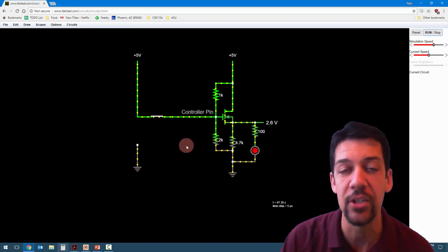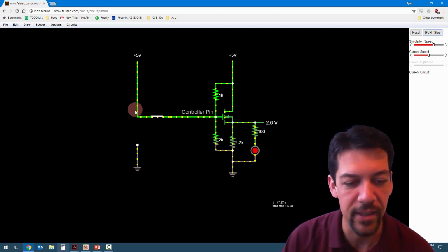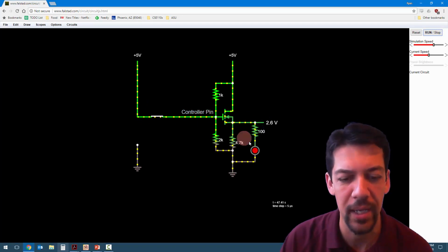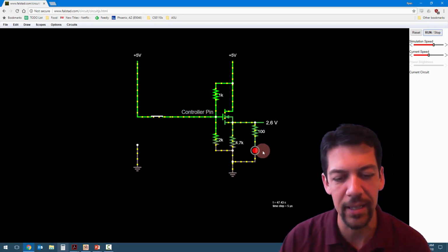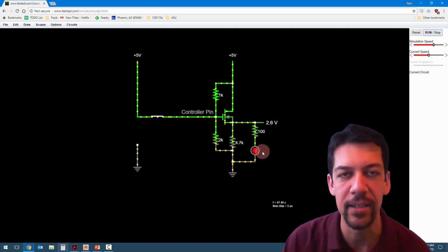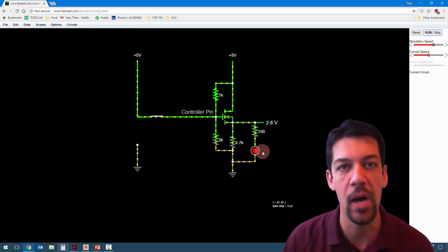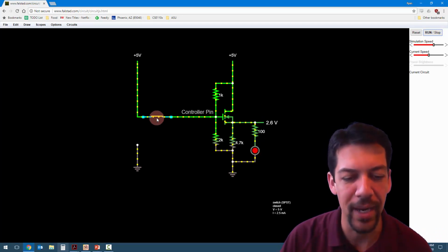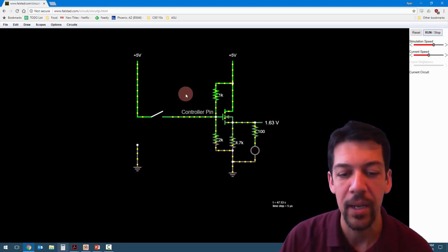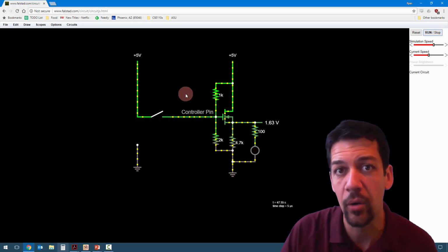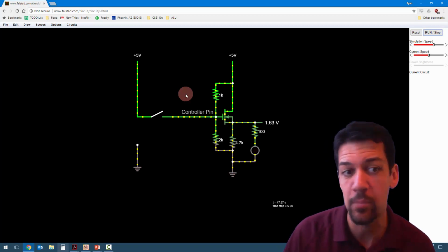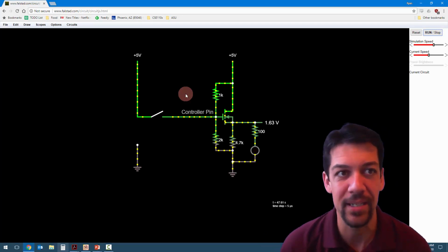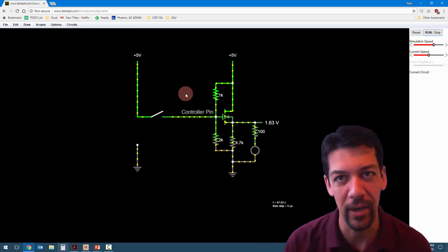When I close the switch, I do get the behavior that I want, in that the current flows through the switch into the microcontroller pin, and it turns it on. So my little LED indicator here in the circuit says, yes, I'm detecting a 1. This is true and on. Great. So the problem remains that when the switch is open, I get a floating voltage. I don't know if that's 1 or 0, and depending on the microcontroller, it might read it as either or both, or it could be basically a random number generator I've hooked up here.